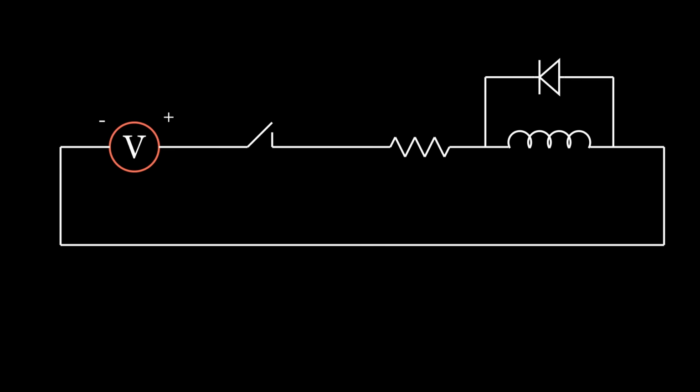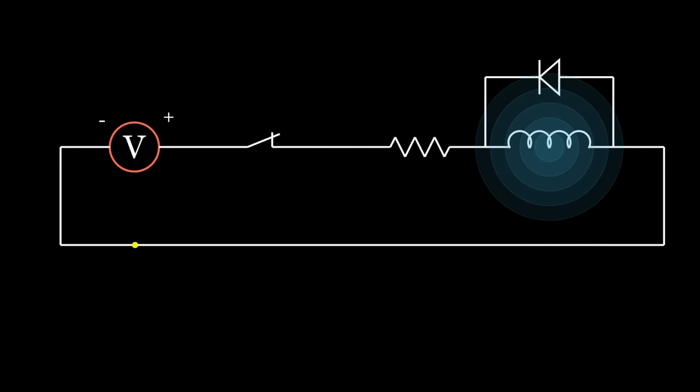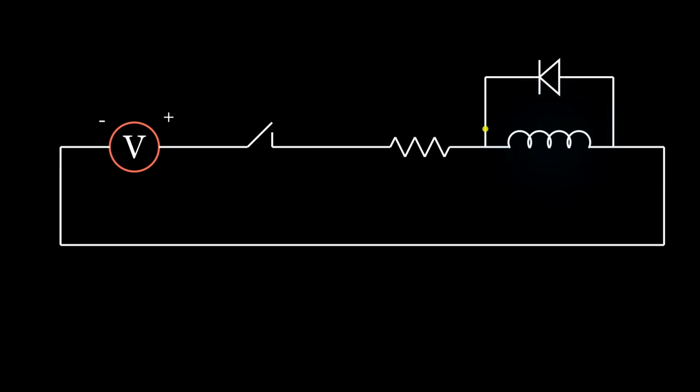Well, all the power we have delivered to the coil to build up the magnetic field needs to go somewhere once the power is switched off and the field collapses. In this case, it is converted back to electrical energy and recirculates through the freewheeling diode and coil until it is dissipated. If we want to minimize the effect this recirculating current has on slowing down the projectile, we need a way to dissipate this energy quicker to reduce the unwanted magnetic field. The way to do this is by using this excess power by putting it through a load, which in this case will be done by adding a resistor in series with the freewheeling diode.